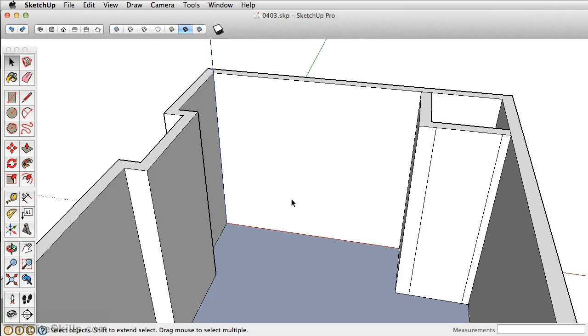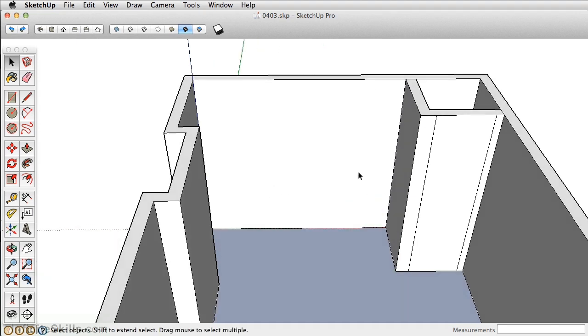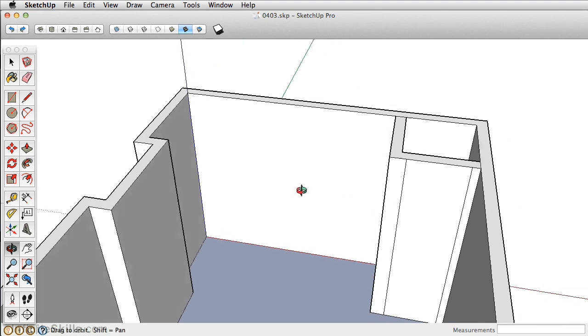Okay, so we have all the walls up, and now we can start creating some of the doors and openings. Let's go and begin in the living room, where we have a large window that's set right here. Now, if you remember in the drawings and dimensions that we had 21 inches from this left wall and 14 inches from the right wall, and then our window opening.